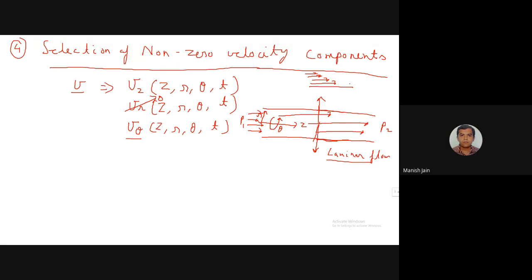So why would the fluid rotate in the pipeline, unless you have some specific geometry which will facilitate the rotation of the fluid, or you have a driving force in the theta direction? Fluid will not rotate inside the pipeline automatically in the laminar flow region. In the turbulent flow region, there are chances eddies will form, and there may be theta directional flow.